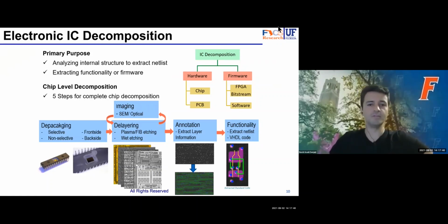So the end user or the entity that wants to install it needs to be assured the IC is what it has been designed to be. We know, in particular with Trojans, based on papers and the literature, there can be Trojans with 10 or 12 transistors among billions of transistors. So assuring that design is important.